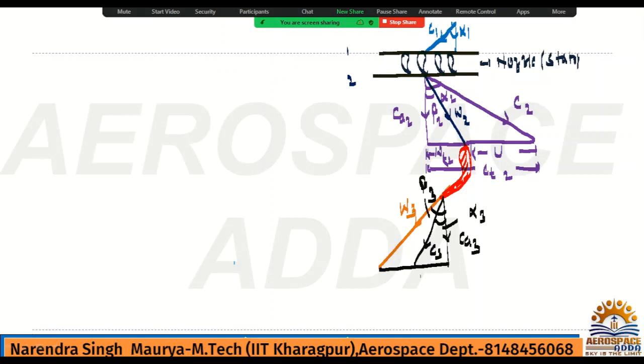Similarly here, the component of absolute velocity will be swirl component, which is CT3, and the vector sum of the relative velocity as well as absolute velocity will be the blade speed, which is U, and the component of relative velocity will be WT3. This is the whole triangle.